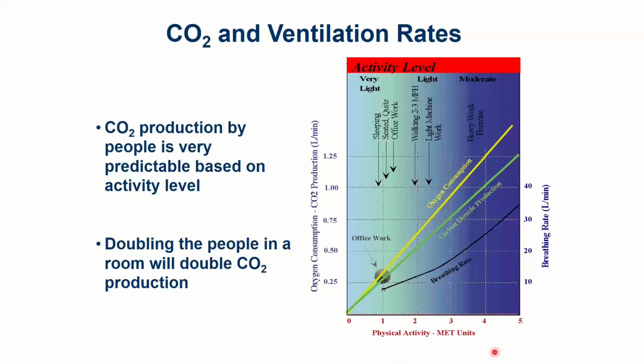I don't really care how much CO2 is in the space. It's not harmful. It's not bad for you. I'm just using the CO2 to count how many people are there. And if I know how many people are there, I know how much bad stuff they're giving off: germs, cough, weird, funky perfume, whatever it is. So I'm really wanting to track people to get rid of people pollutants, and CO2 is my way to count the people.